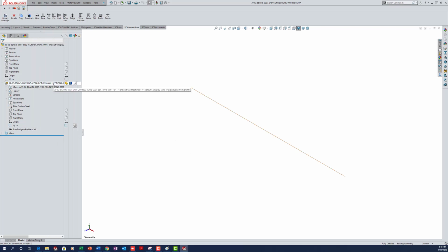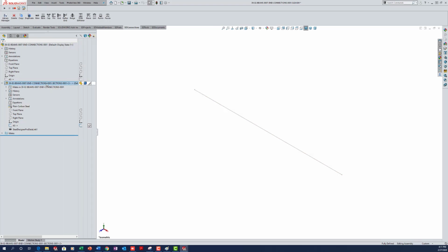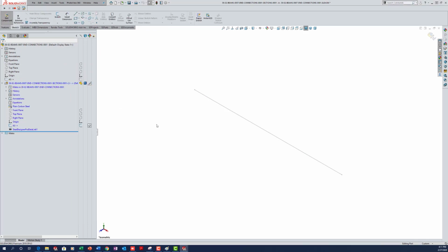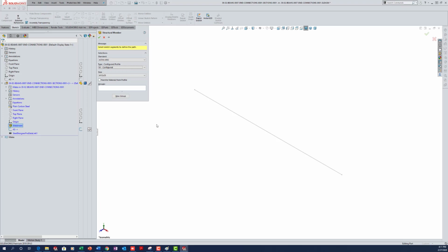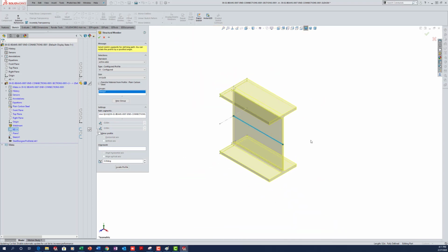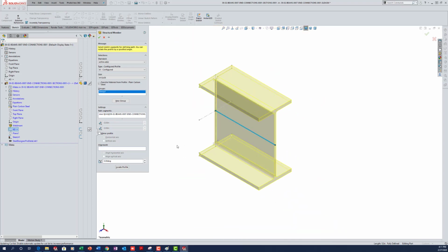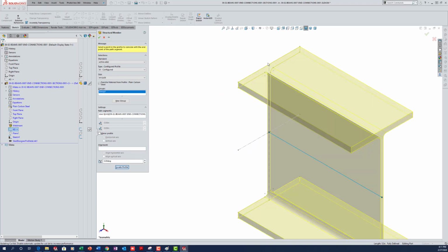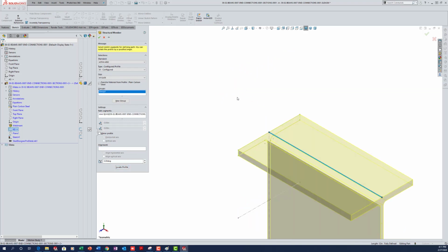So there's already an enveloped section 1 in here. We're going to take and edit that part and give it a weldment profile. Make sure you have the correct sketch turned on. We'll locate the profile top of steel, as it will be. In Steel Designer Pro, your weldment profiles are not rotated and they're not mirrored.